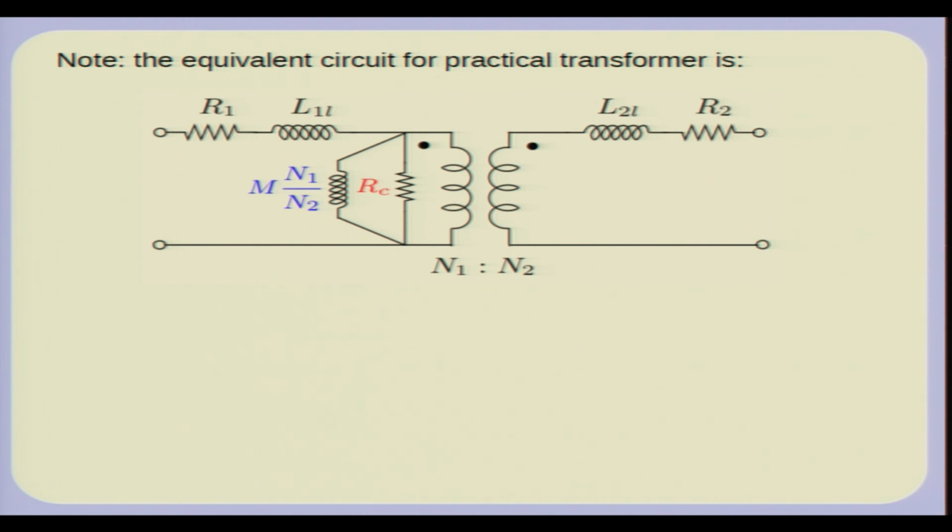So, what you can do is make some approximations. For example, during the short circuit test, you can neglect the current flowing through this. The reason is of course that this current is usually much smaller. When you do the short circuit test on a transformer, what you do is apply a small voltage to one side and short circuit the secondary. The current is high, but since you apply a low voltage, you can restrict that current to the rated current of the transformer, so on the primary and secondary respectively, only the rated current flows.